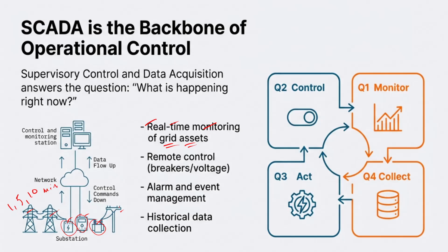There will be different components within the substation, right? It could be a circuit breaker also, correct? So this is all the real time monitoring that we need. To do the real time monitoring, basically we need parameters like P, Q, and also V and the frequency, right? Here everybody knows, this is the active power, the reactive power, the voltage and the frequency.